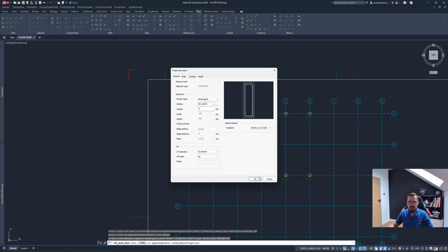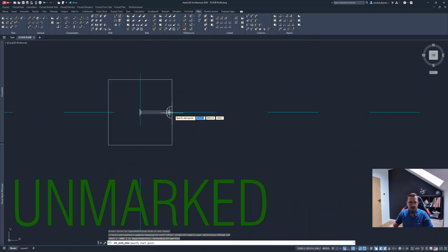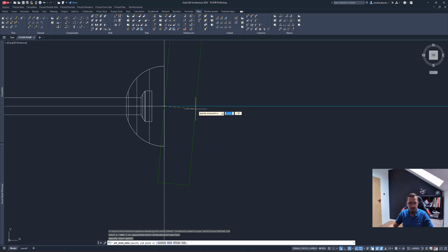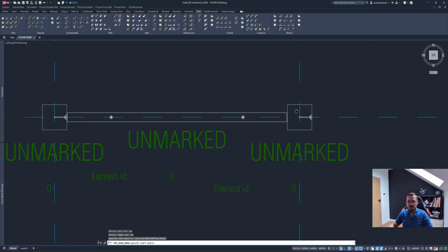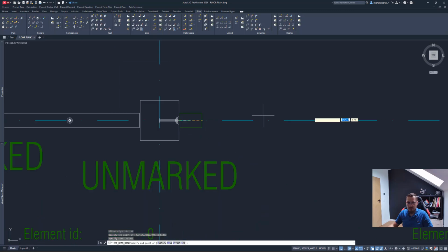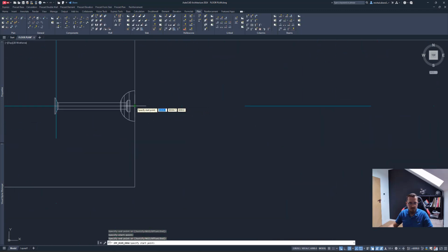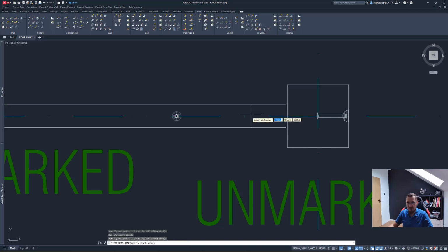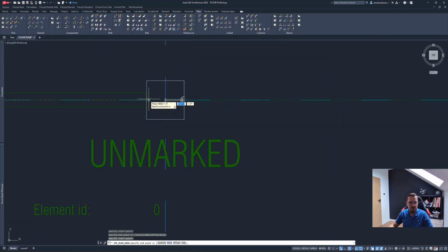I don't really want to modify anything else in this particular scenario. I want to specify the first point here. I also want to apply offsets, so they're not exactly flush with the columns, because that's offset left and now offset right. And as you can see, we are now offset with the beams. Leaving those elements flush is not exactly perfect. Simply put, it might be hard to place those elements on site if they're flush, or we might crack some concrete or do something we don't really want to do.